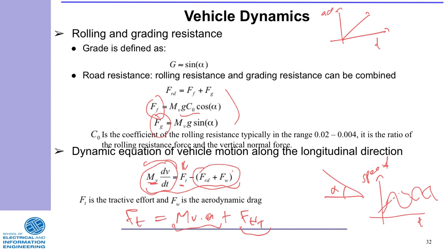So it means now one has to size the internal combustion engine based on these requirements. Let's say you want your vehicle to be able to accelerate from 0 to 100 kilometers per hour in 10 seconds. That is factored in this equation, in addition to the fact that it's not only acceleration that the vehicle should be able to do. It should be able to accelerate like that and at the same time overcome the forces that are acting on the vehicle.